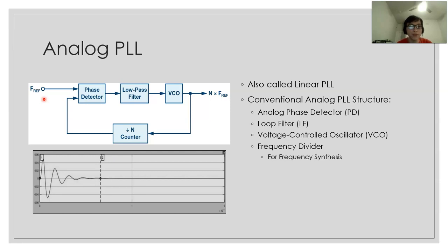This is a very important application of phase lock loop, as it can use an input clock signal at a low frequency to minimize the power consumption of the oscillator, but then it can create a clock signal at a much higher frequency according to the needs of the circuit.